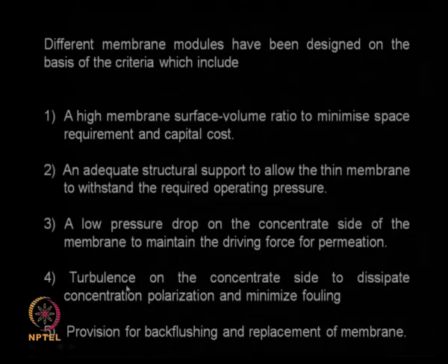We want to have good turbulence, so that we minimize fouling and minimize concentration polarization. We should have provision for back flushing and replacement of the membrane. That means after 1000 hours or so many 100 hours, I should be able to back flush and remove the foulant.